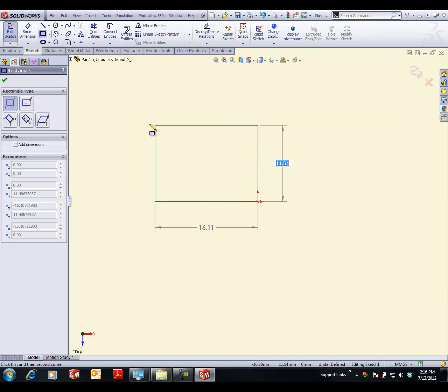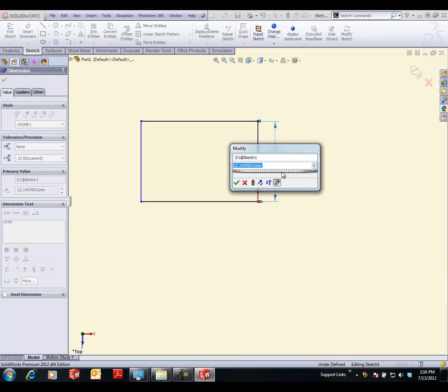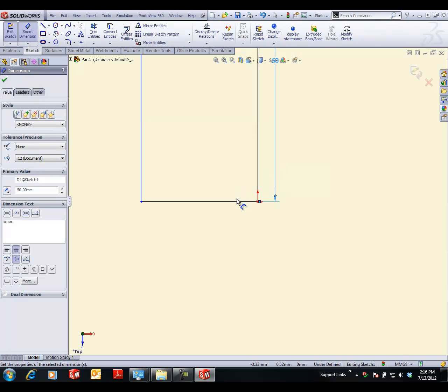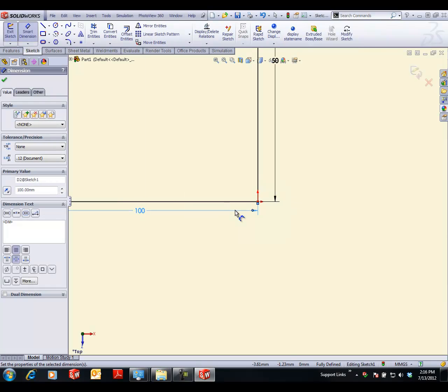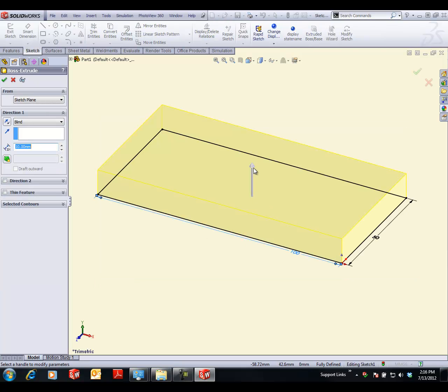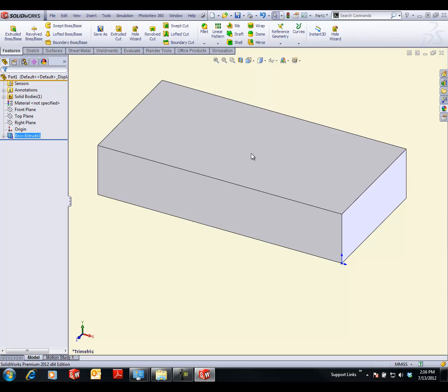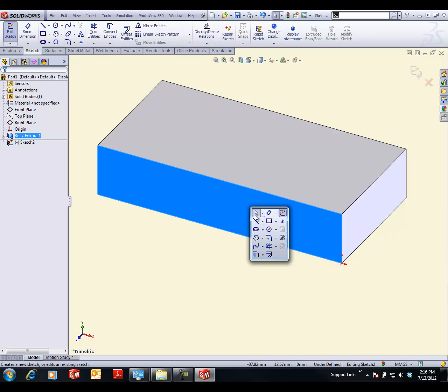Things such as the quick toolbar right there when I hit the S key, bringing up the most popular used commands. Also right mouse button holding and gesturing for the command I wanted. Notice how fast I went into the measurement tool. Hitting F on the keyboard to do a zoom to fit. I just did a mouse gesture to the right to do an extrusion. So these are things that are making your life easier today that are just amazing.